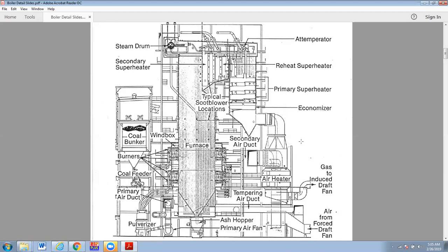So you have multiple ports in the boiler that are supplying air well beyond what comes in with the primary fan through the coal pipes, and then the wind box, injecting air directly into the area where the fireball is probably the hottest, and then we have secondary and overfire air and all kinds of different air ports on further downstream. So that part is fairly complicated, and these diagrams don't really do it justice.